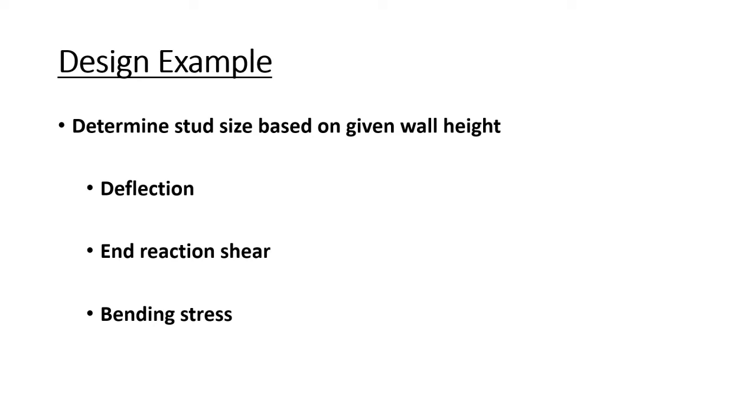The equation is based on limiting the span by a ratio that takes the flexibility of the finished materials into consideration. For example, a gypsum panel with a paint finish is more elastic than a finish of gypsum plaster in paint. The gypsum panel is then limited to a deflection at a ratio of L/240, where L equals the span in inches.